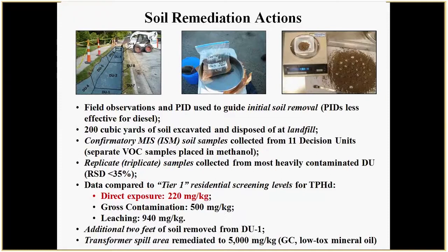In each one of these areas, we collected a 1 to 2 kilogram sample from 30 or 40 or 50 points, combined it together, and sent that to the lab for testing. So we get much more representative data, much more reliable data for cleaning up a site.